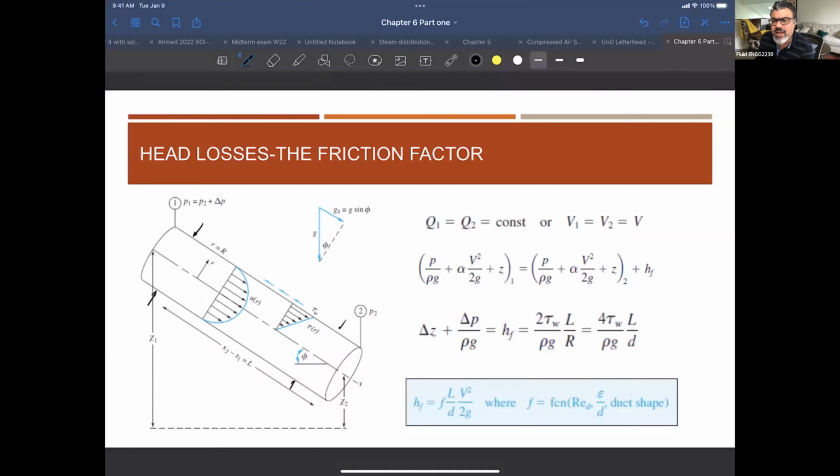Of course, within the fluid itself there are also some viscous forces, right? That's why when you look at the velocity profile here, the velocity here and the velocity here are different. What is changing the velocity between this point and this point? What is the main reason for the fluid velocity to decrease as you go closer to the wall?